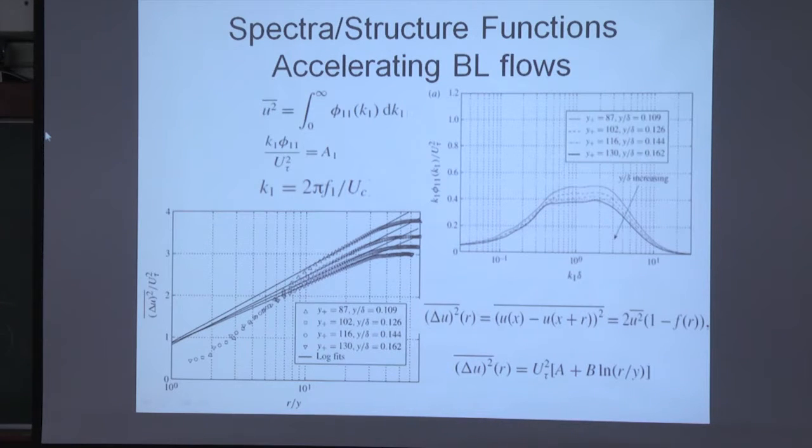Okay, now this is about the spectrum. I told you about this very controversial thing. I must say that is one of those elusive things in the literature. What is plotted here is what is known as the accelerating boundary layer flow. We are exploring under what conditions you will get this k minus 1 spectrum. This phi 11 is the spectral quantity which is plotted, and if I integrate this, I will get the kinetic energy, what I called E earlier. We use the symbol phi 11 here. Okay, it's the spatial spectrum.